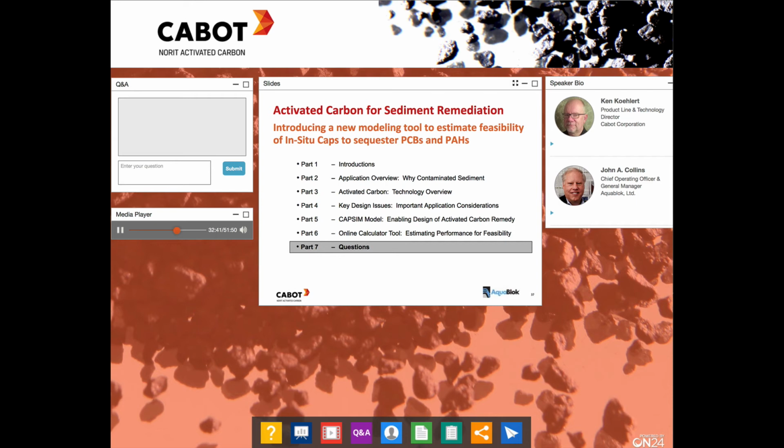Okay, I've got a question here from Matt, and I think it relates mostly to the stability of the materials as installed. The question is, do you have any information on winnowing or erosion of PAC once disaggregated from the AquaBlok or the sedimite? He's really wondering about stability in the sediment over time.